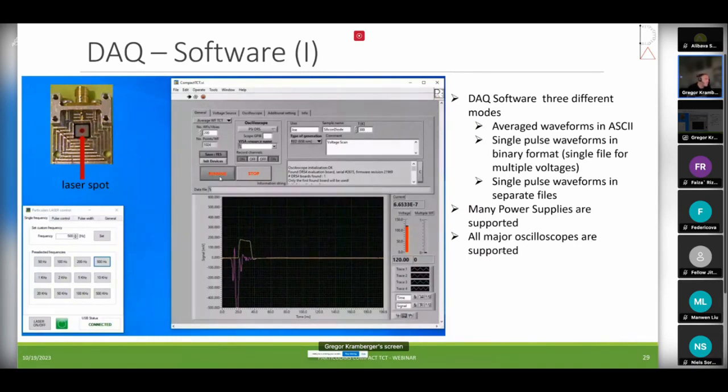And you can clearly see that once you are very high with bias voltage, you stop. This increase is almost negligible. It looks flat because the drift velocity is saturating, and this is something that students also look at when they do this. Okay.